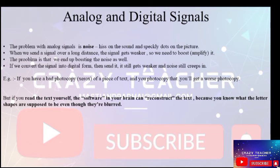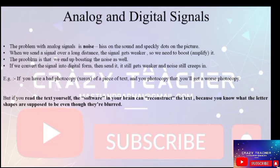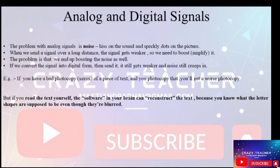So you can think about these different signals as digital or analog, but most of the common signals that we have are analog in nature. So we have to pass them through an analog to digital converter to get the corresponding digital versions. And if we are trying to produce an analog signal through some digital processing, we have to have a digital to analog converter for converting the digital value to analog.